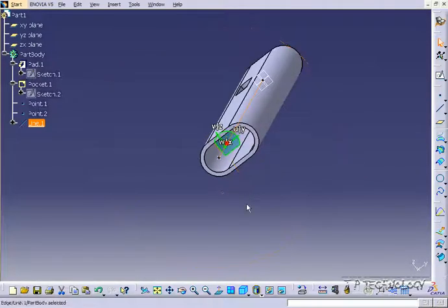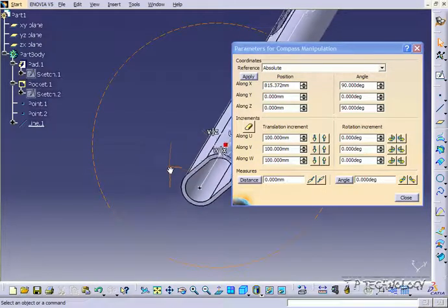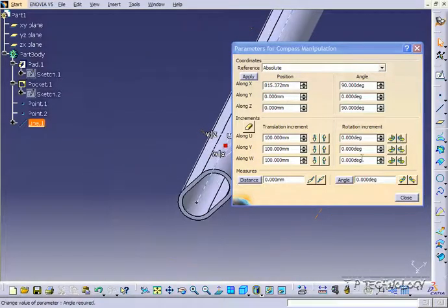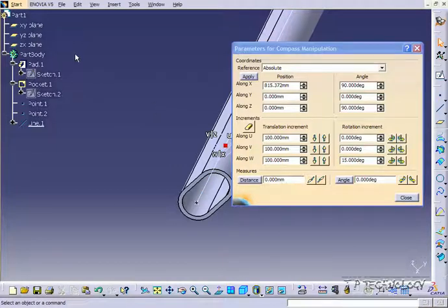So now once you've done that, like the translate feature, you're going to have to highlight everything, and you're able to rotate it either by clicking the plane you want to rotate around or by double clicking on it. So let's double click, and all your rotation increments are on the side here. What we're going to want to do is rotate around the W. So let's make it 15 degrees. And now let's choose the part. So we're going to choose this part.